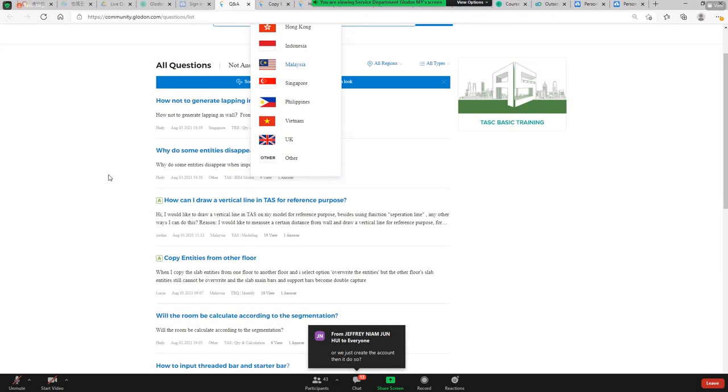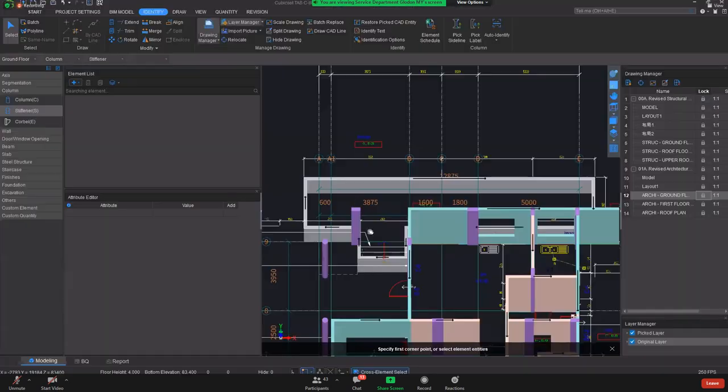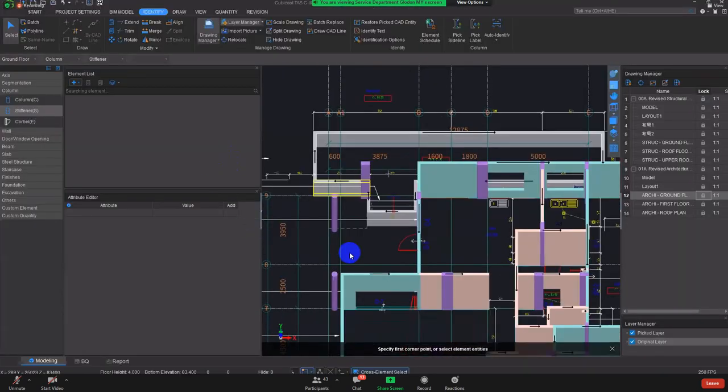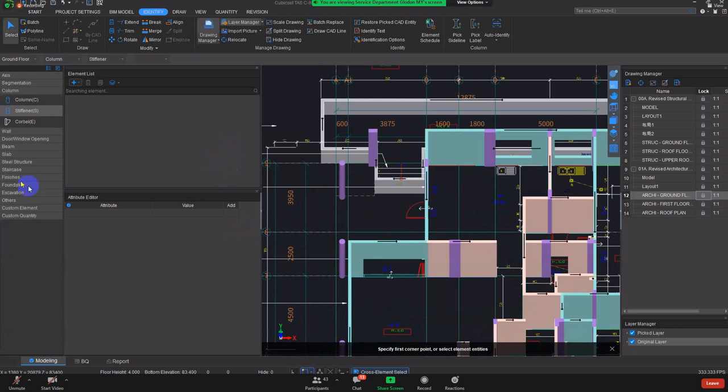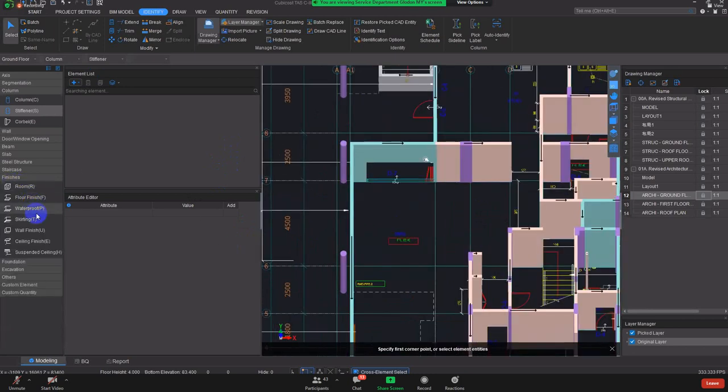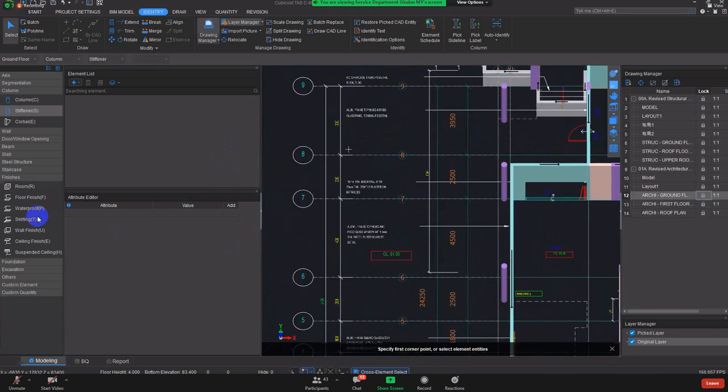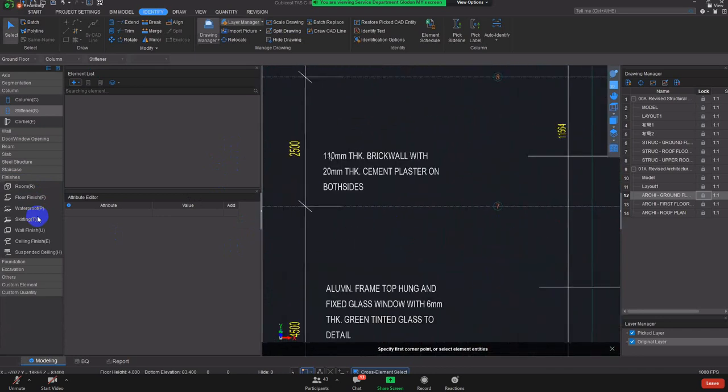Right, C and WH. The 150 mm thick wall is including plastering, excluding plastering. Do we need to deduct the plastering thickness? Right, so for the drawing here, in our software, this is only for the brick wall without the plastering. If you want to have the plastering, it will fall under the finishes category. In your real practice, 150 mm, this is 110 mm, in fact, the 150 mm includes both plastering. For these training purposes, I just include 150.